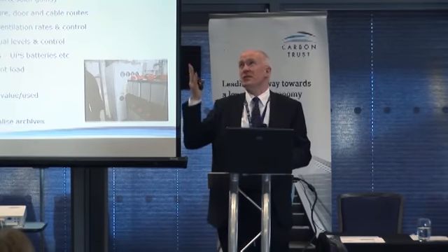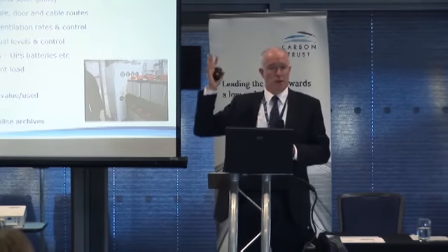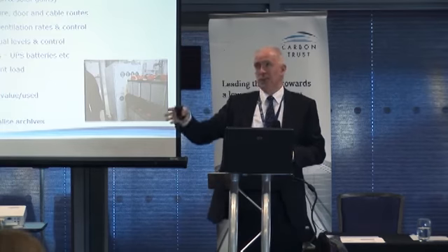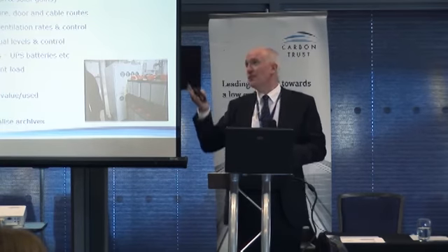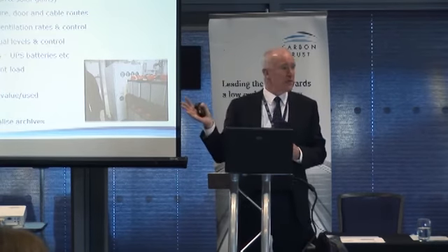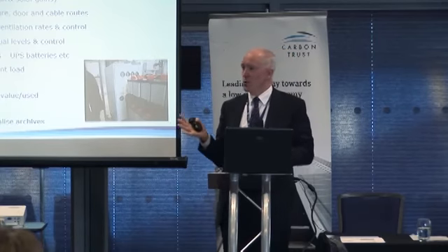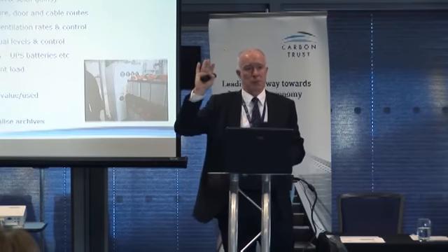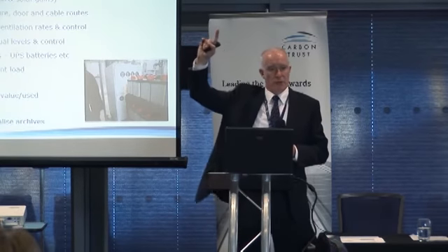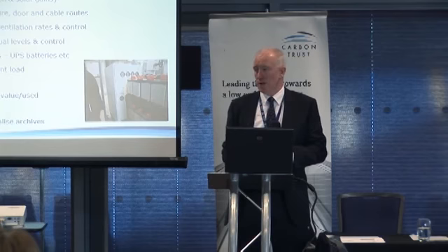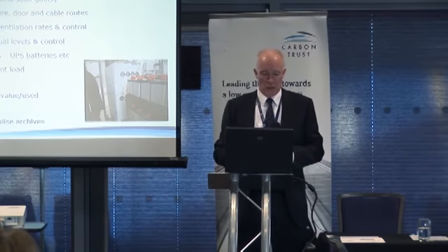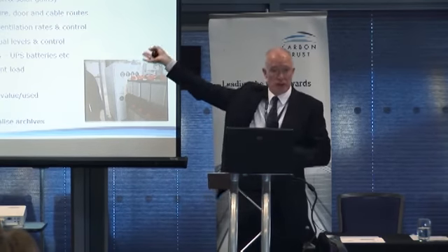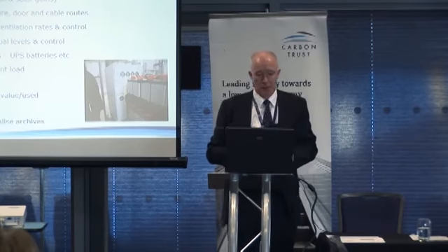The biggest thing is suspended ceilings, which are standard within our computer rooms. Where the cables come down from that suspended ceiling, often people have taken the tiles out. The tiles are half broken. Is that quite common? I find it all over the place. We need to seal those suspended ceilings up as much as possible. So where your cables go through the ceiling, make sure the ceiling tiles are continuous and well in place. Otherwise, you're just air conditioning the whole of the ceiling void sometimes.